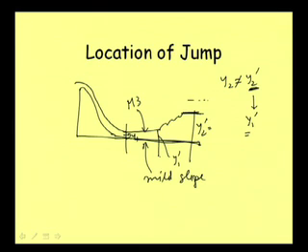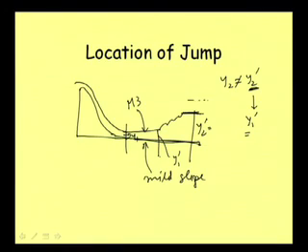Our understanding of computing gradually varied flow profile is now coming into play. In this M3 profile our upstream depth is y1 and downstream depth is y1 dash, so from here to here we can compute the M3 profile, and this will give us the length of the M3 profile.